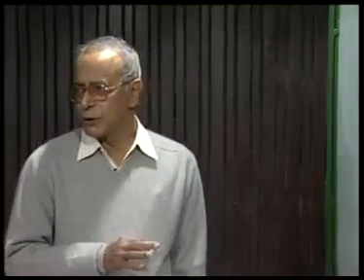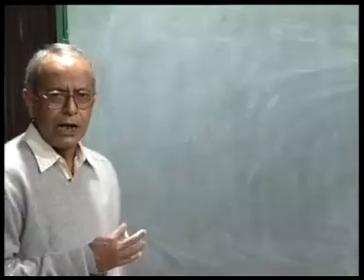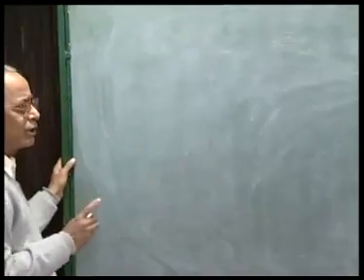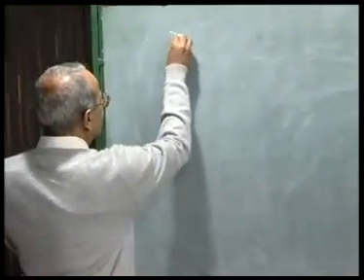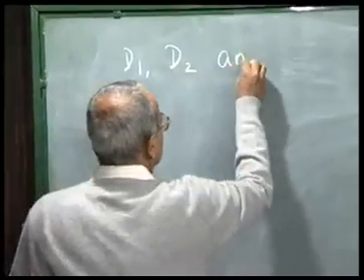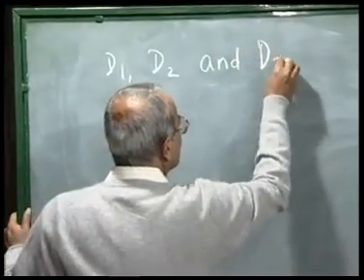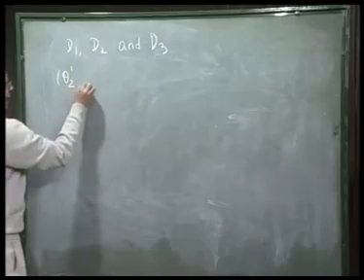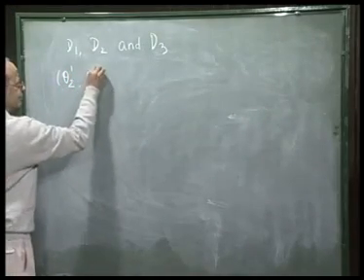So, we have discussed the function generation problem with reference to a 4R linkage function generator for three position synthesis. What we emphasize is that we got linear equations in the design variables, namely D1, D2 and D3, only because we assumed theta 2 1 and theta 4 1.